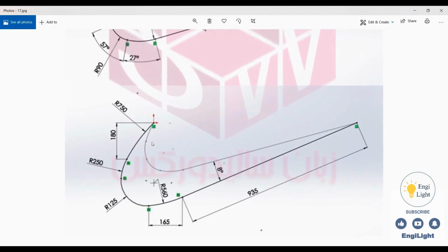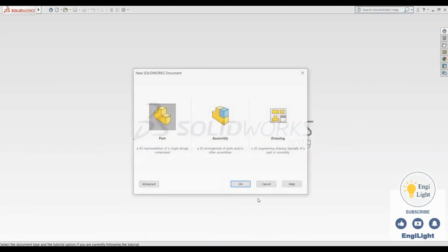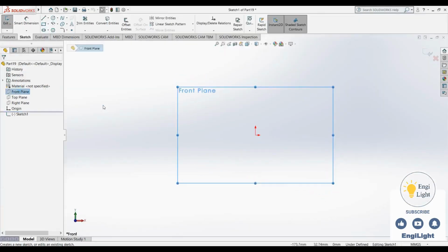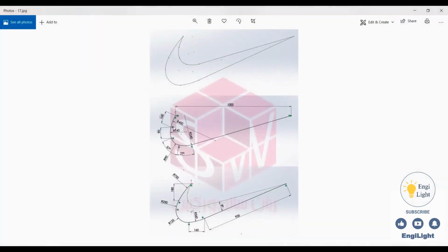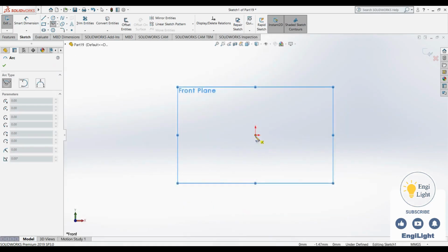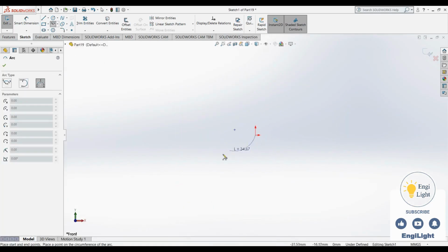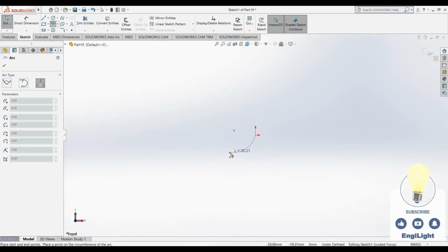As I mentioned, to create this sketch, I fully define each curve one by one before drawing the next. So I open a sketch on the front plane and start drawing using the arc tool from this point. I select the third type and draw the shape like this.